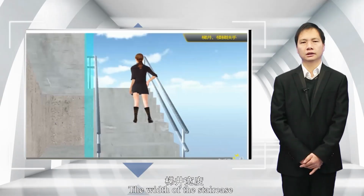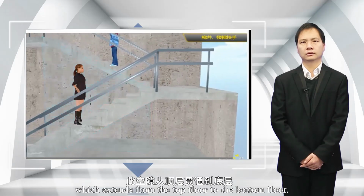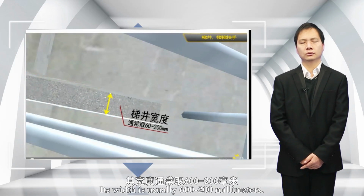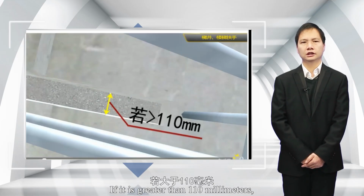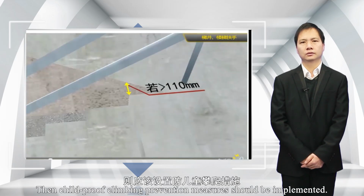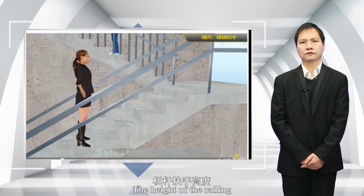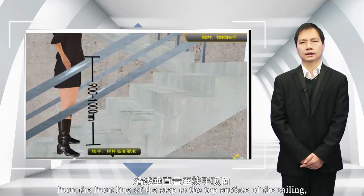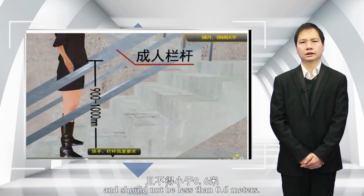The width of the stairwell refers to the gap formed between staircase sections, which extends from the top floor to the bottom floor. Its width is usually 60 to 200 millimeters. If it is greater than 110 millimeters, then child-proof climbing prevention measures should be implemented. The height of the railing should be measured vertically, from the front line of the step to the top surface of the railing, and should not be less than 0.6 meters.